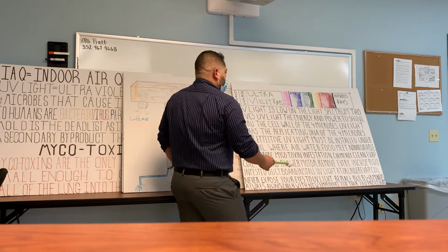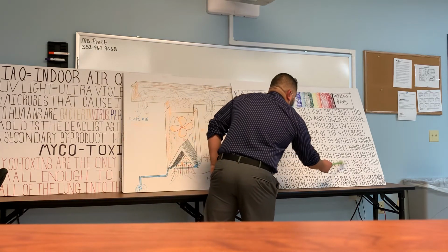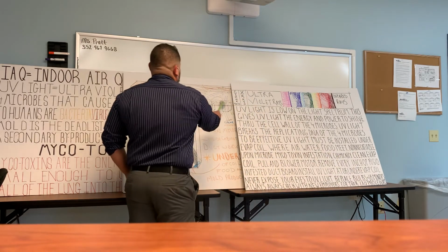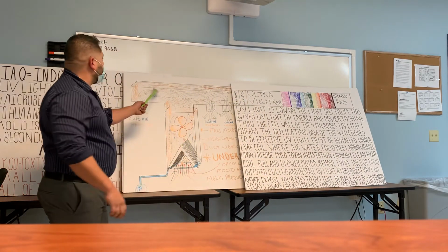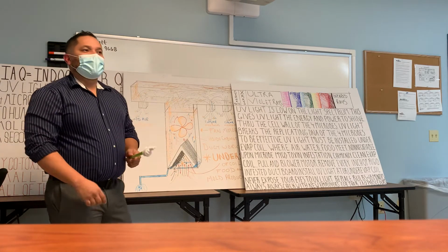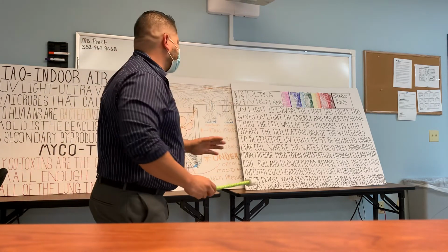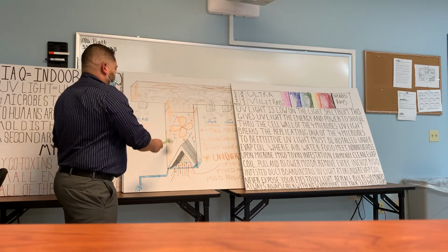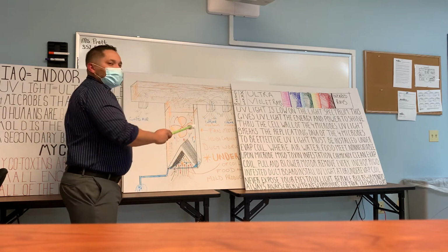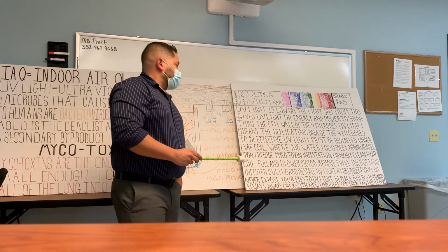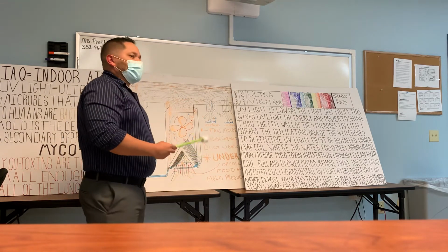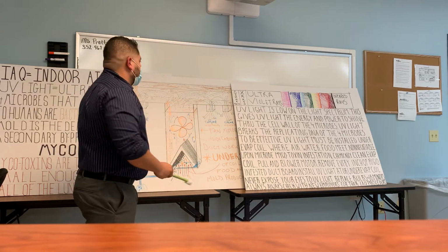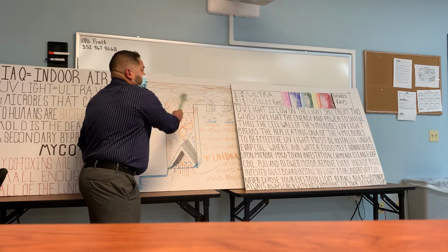Next, what we're going to do is we need to remove every inch of rigid infested ductboard. That's all of this ductboard. We said earlier this was rigid ductboard. It's porous inside. It's impossible to clean mycotoxins off this. There are some people that say they can just put a light here or put a spray here and they clean the duct system. You've got to be very careful because you don't want to give a client a sense of, oh, well, we'll just spray something in the ducts and it'll be clean. With rigid fiberboard, it all has to come out.